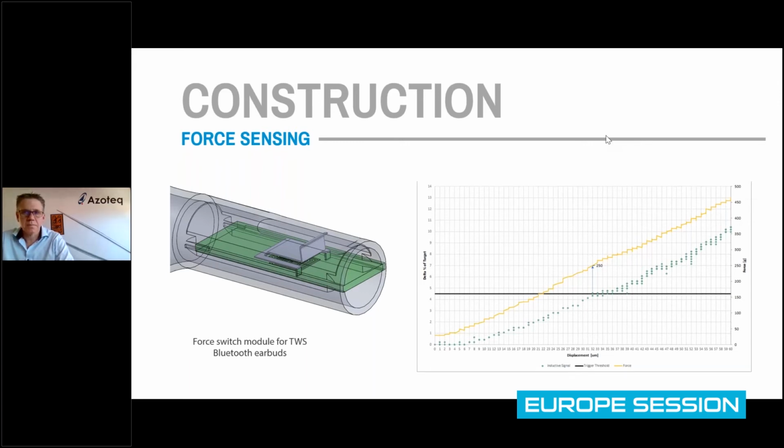So in a design for inductive sensing, how many coils do you have? Is this only one? Or do you mean how many turns on the coil, or how many coils? Not turns. How many coils? Something like the 269, which is most widely used in true wireless. The IQS269 supports 3 coils, and our new upcoming IC, the 7210, can support 4 coils from a single IC.